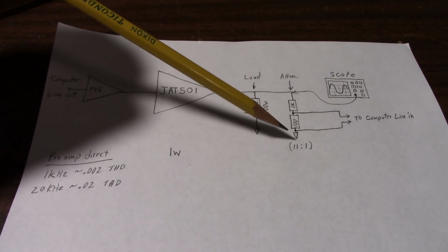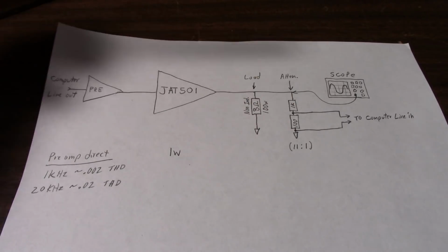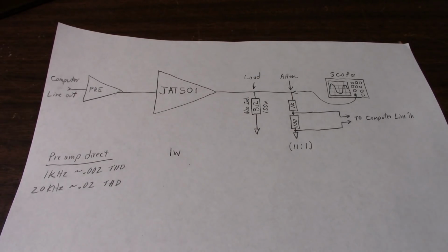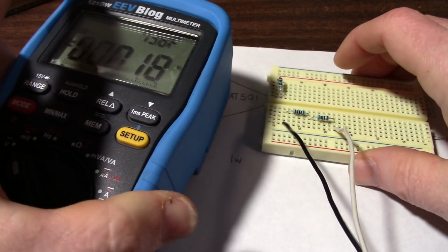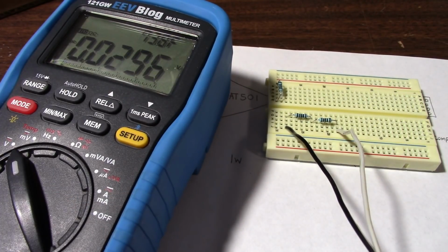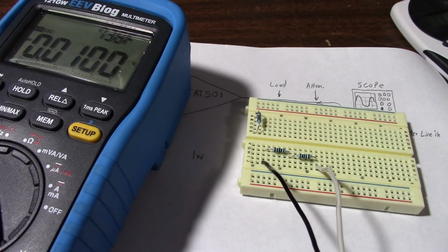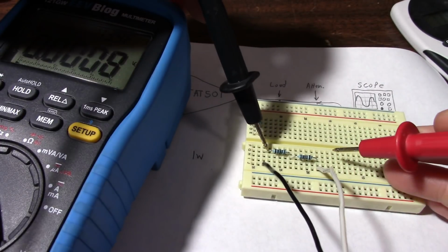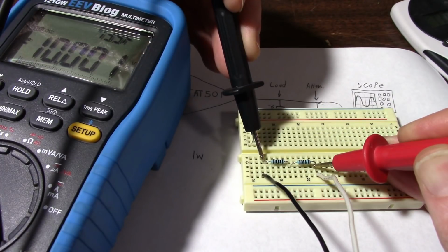So this turns out to be an 11:1 ratio. Why do I say 11:1? I mean, it's a 100 ohm and a 1K. Isn't that a 10:1? Well, let's take a look at this real quick. Here are the resistors, which I'm going to use. Get the meter into the shot. I have the power supply set up for 10 volts. Now let's try this again. Knocked the camera over, trying to get the leads in here on it. So if I don't block the meter, exactly 10 volts.